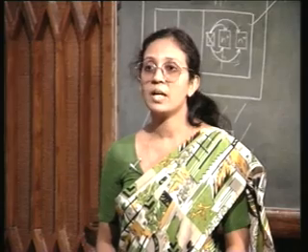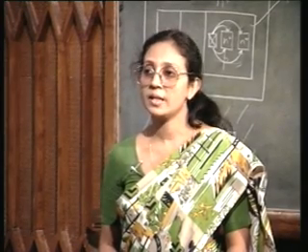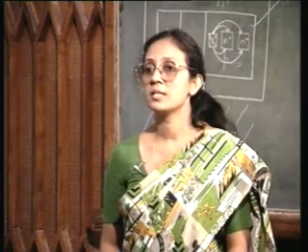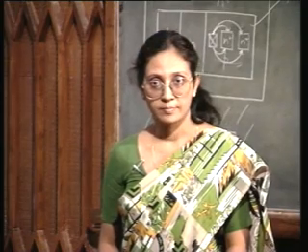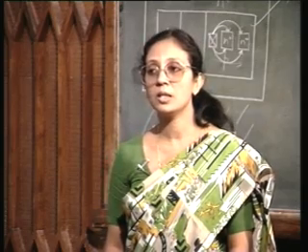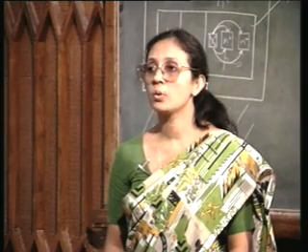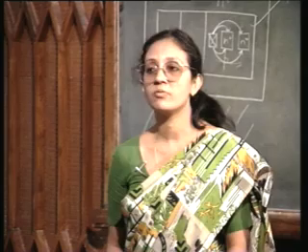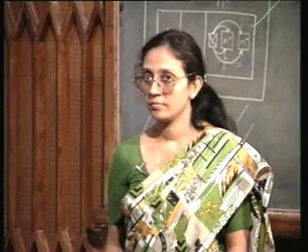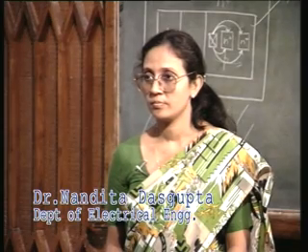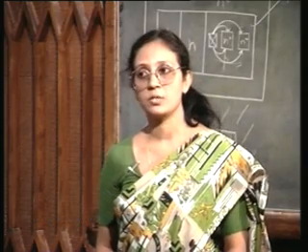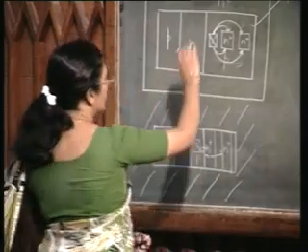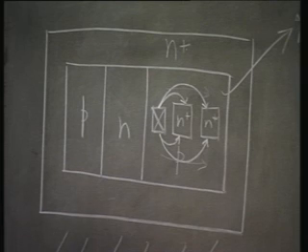And whenever I have the current flowing underneath the collector, I am making it flow through a constricted region, and therefore, the resistance in that path is going to be larger. So, I will have unequal voltage drops, and which will lead to unequal drives. Remember, the multiple collectors actually represent the multiple fan outs. So, different fan outs will receive different drives. Okay? So, this is the problem in the oxide isolation case. By removing these rails, which we thought was the unwanted region, by removing these additional P regions, we have indeed saved a lot of space, but in the process we are having unequal drives.